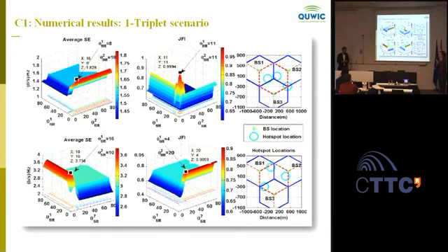Yeah, the tilting is usually also used for coverage and interference control. So maybe, if you tweak another metric, not the capacity metric, which is rather where the beamforming goes in, you get the good complement. But it's a good example of two SON functionalities, the beamforming and the tilt, maybe giving contradictory instructions. So then you need to decide whether for you it's more important to keep coverage and minimum quality of service in place, or whether capacity to a specific set of users is more important. Yeah.